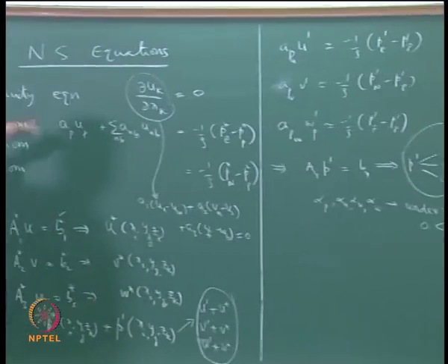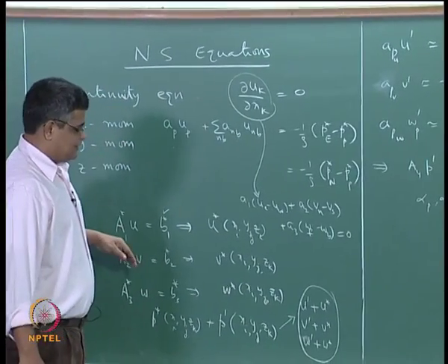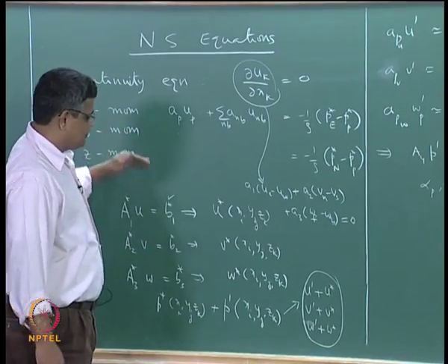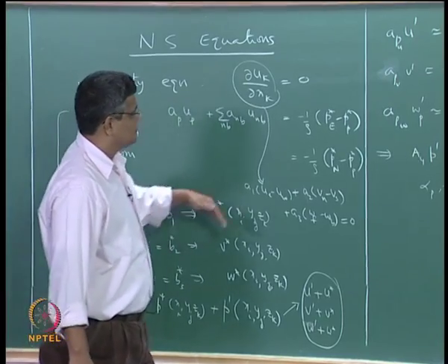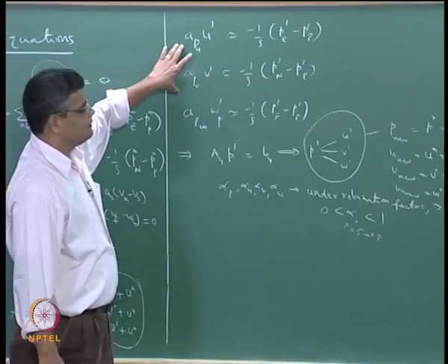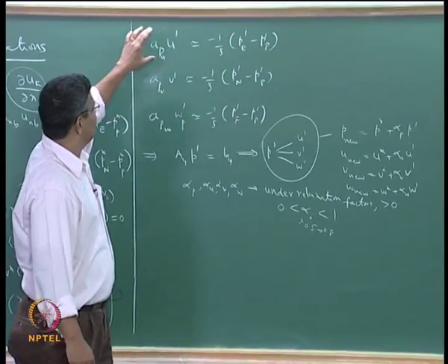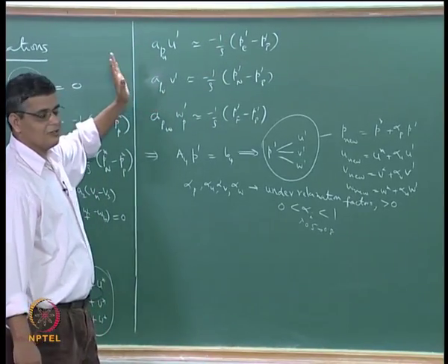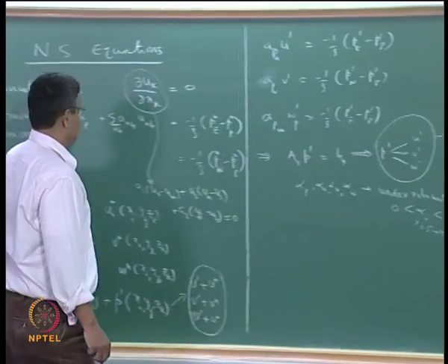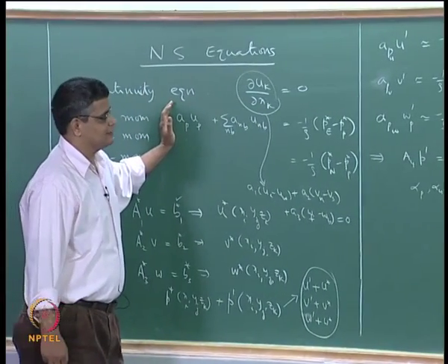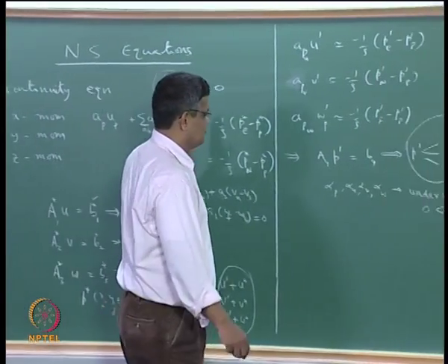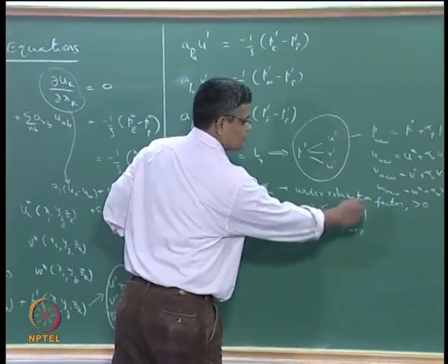Okay, so what we have done is, through this discretization here, making the approximations for this influence of the pressure correction on the respective velocity corrections on a simplified form of the discretized momentum equation, we are able to go from the old values to the new values.